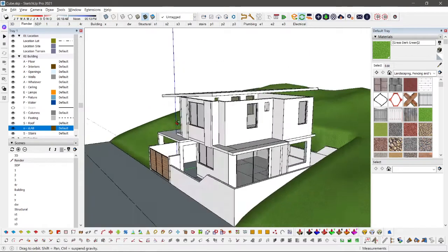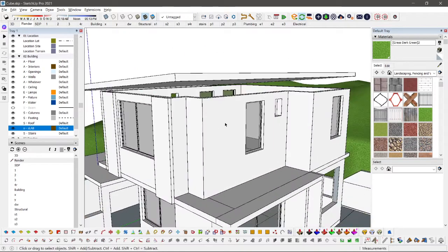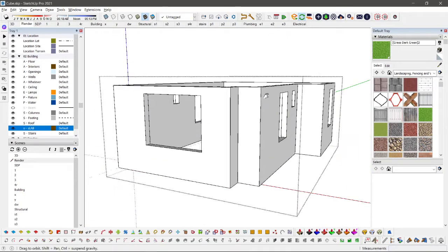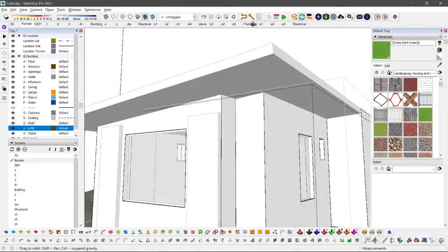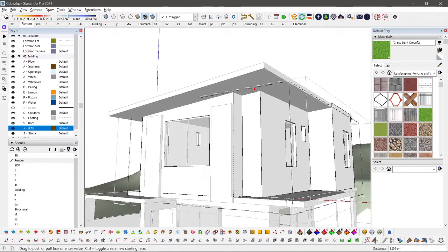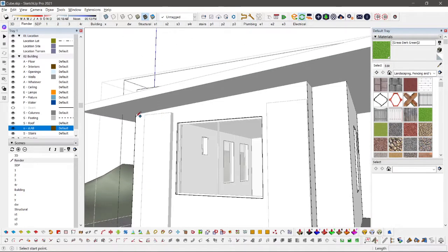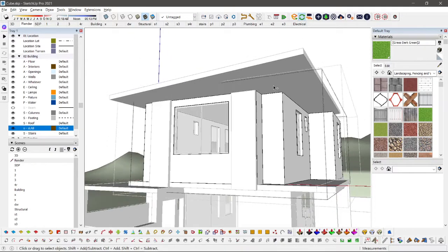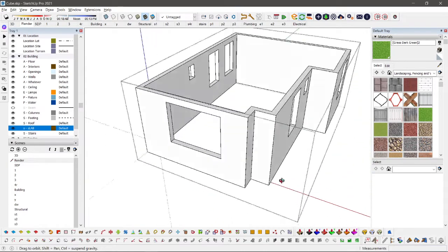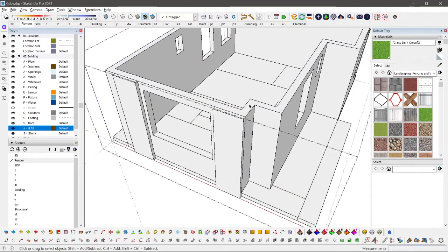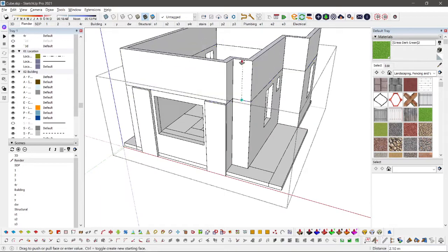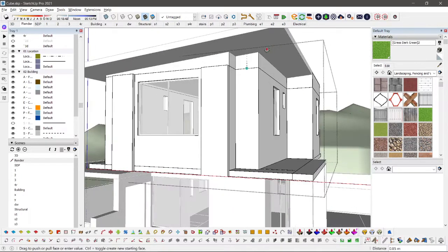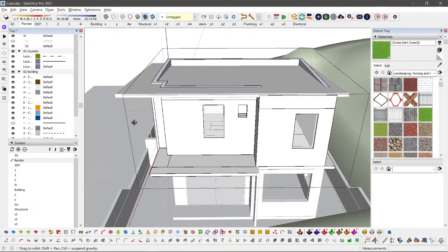Oh, okay. Now in this case, many people try to extend the walls upward and cut them based on the roof. The problem here, however, let's say you already cut this and put the diagonal, is that if you have revisions, you're gonna have a hard time. So what I do is I just select the upper wall and make it into another thing. Let's just say from the roof beam towards the roof will be something different.